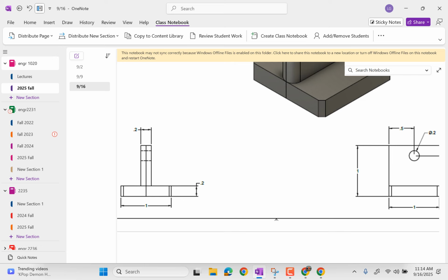So I'm going to make this base piece that's only half an inch long, 0.2 inches high. This is going to be 0.1 inch thick, and what's the height? 1 inch, looks like, yeah. And I'm going to cut the hole out of it. And then we'll do the chamfers and the fillets, and then we'll mirror everything. Okay.